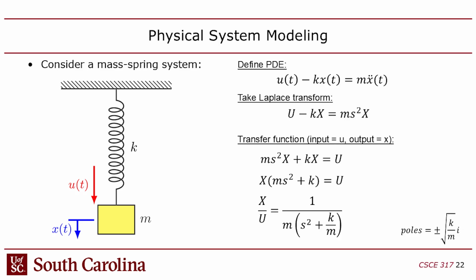Right? So someone might say, well, how is that unstable? You're telling me that this thing can go infinite? How? Well, if you have a spring and I go like this and I put a certain frequency into it, if I put the natural frequency in, this thing will go bigger and bigger. Imagine I was holding a weight with a spring on it, and you hit a certain frequency and it keeps getting bigger and bigger and bigger. Now you might say, well, eventually the spring's just going to break. That's because it's nonlinear. True, but there's something else happening there too that's making it actually bounded.